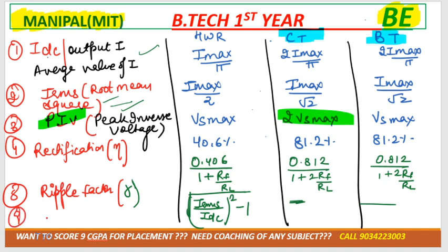Okay. One more thing, write it down over here only. It will be on the same page then. Sometimes they'll ask you the output frequency. Output frequency is denoted by F. For a half wave rectifier, it would be the same as the original frequency F. For a full wave rectifier, it will be double, twice of F. Okay?